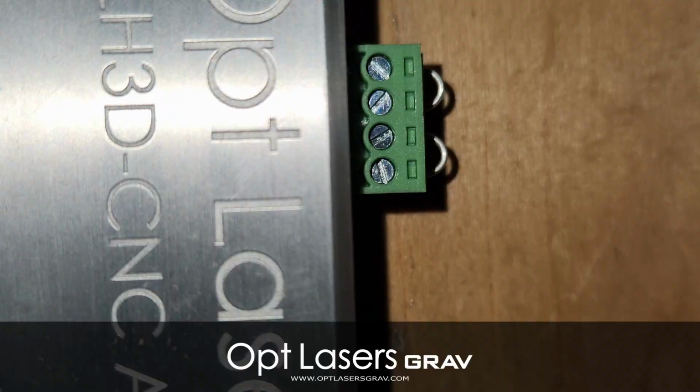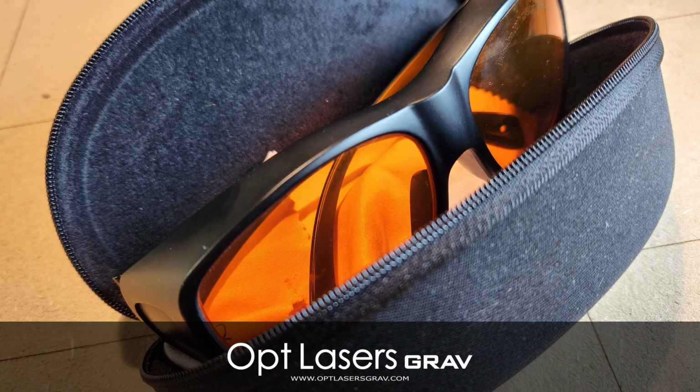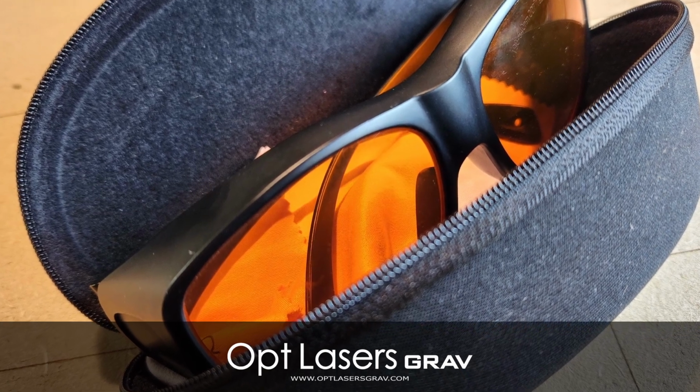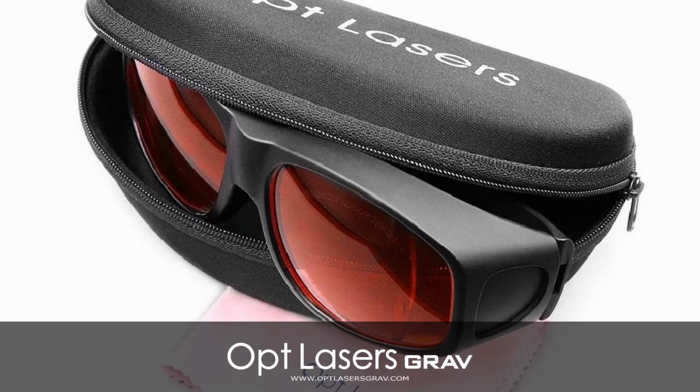At this time, we should make sure that all connections are safe and secure. We are going to power the CNC adapter, which is going to arm the laser head. Anytime the laser head is armed, you should be wearing protective eyewear. The reflective light from the blue laser can cause permanent eye damage.